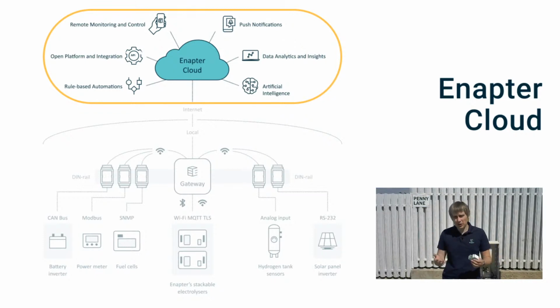Afterwards, you develop your way of acquiring the data from the connected device. So actually, you implement the communication protocol. In case in your heating room you have a boiler which supports RS-232, you just implement this serial protocol in Lua, and you upload it to this module. After that, the data is delivered to our cloud and also visible in our application.